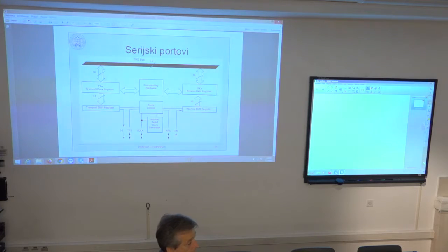And by servicing this interrupt routine, you would take this word from this peripheral unit and write it into some memory buffer or directly process this data value with your algorithm. So these serial ports are already available on this archaic DSP, but nowadays they are much more complicated than those described here. Okay. Now we'll make a break.